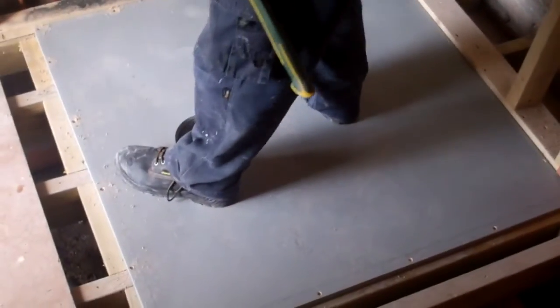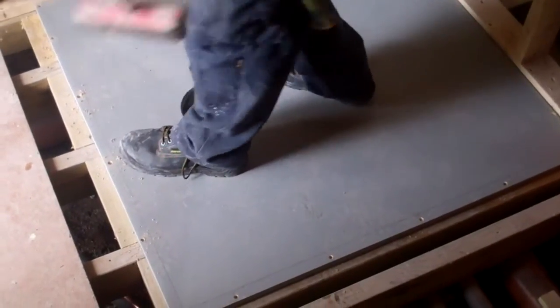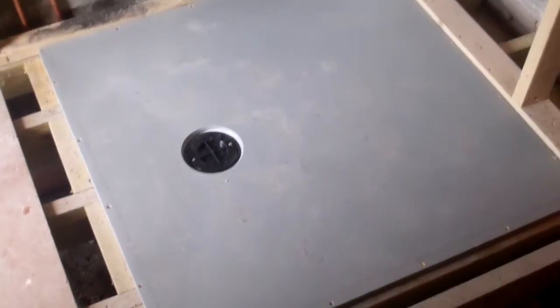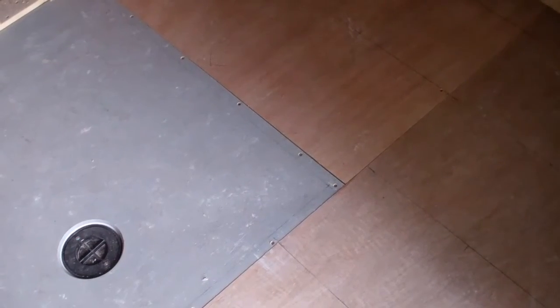Sweep off the tray before installing the rest of the floor. The flooring in the wet room must match the thickness of the Aquatechnic shower tray former, which is 24mm thick. This can be achieved by installing 6mm thick WBP plywood over the top of an existing 18mm flooring, or better still, replacing the entire floor with 24mm WBP plywood.